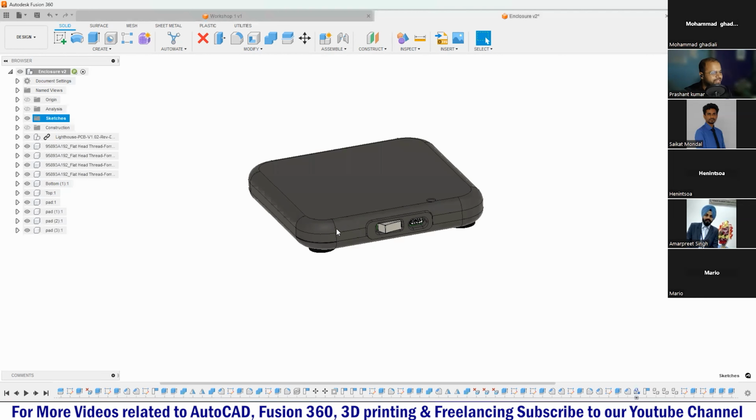For example, if we have a 3D model and I want to zoom in, I can just rotate my mouse scroll wheel, and here you can see I'm zooming in and zooming out. It's very simple, like any other CAD software. Then if I want to move my model across my space, this is actually called the pan tool.